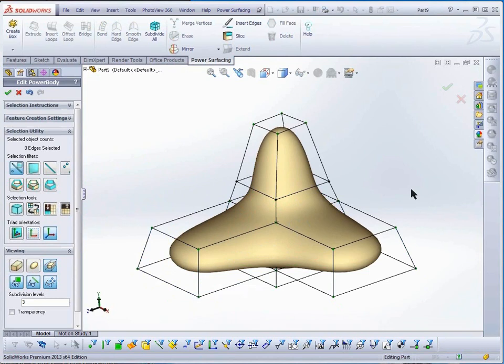With edges, the A key will allow you to drop edge loops in quickly. Hold the A key down, then hover over an edge. A red preview edge is shown. Picking will create the new loop.